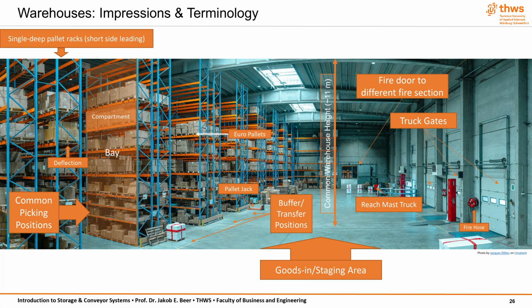Furthermore, the height of the warehouse determines the type and configuration of racking systems. In mid-height warehouses, say around 10 to 12 meters, it's feasible to use static pallet racks operated by forklifts. However, once buildings exceed 15 to 20 meters, automation becomes not just more efficient, but often necessary. ASRS systems, stacker cranes, or shuttle systems are typically deployed in such environments to ensure safe, accurate, and high-throughput handling of goods stored at significant heights.